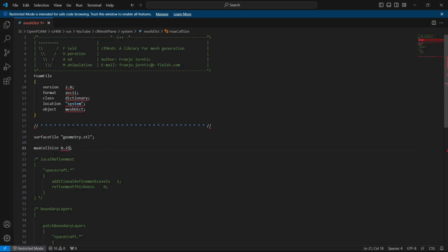And let's say initially our mesh size is 1, because ours is in the order of meters, right? -6 to +6 and all. So this will be a very coarse mesh. It's a very bad mesh, but we will just see what it does. Now we have given the input parameter .stl and the mesh cell size as 1.